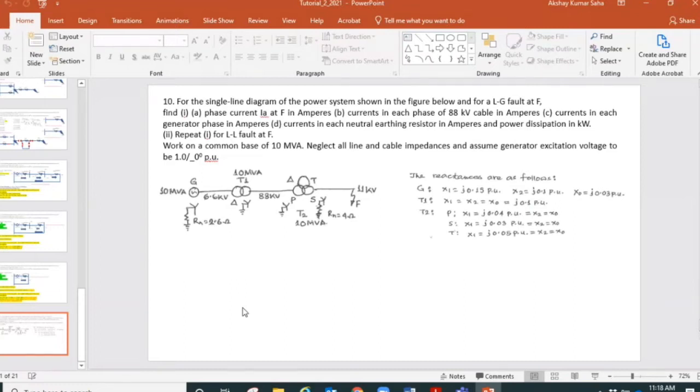So when you go from a delta to star connection, you might find that there is an angular difference between the delta side voltage and the star side voltage. Because of that, you cannot just go and connect that shifted voltage to any other thing. That will cause a circulating current in between the two. Does it make sense?